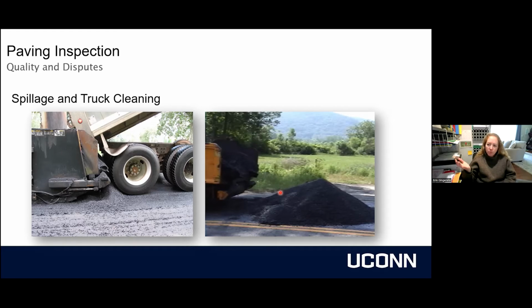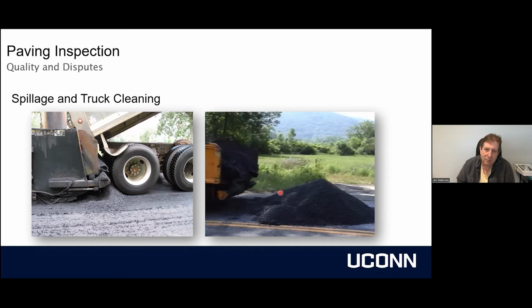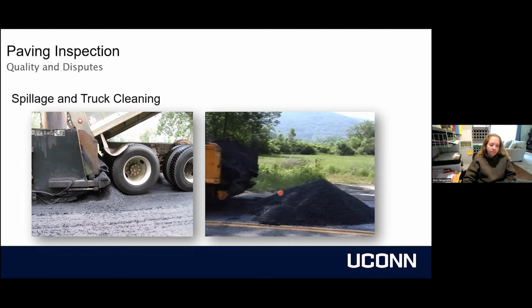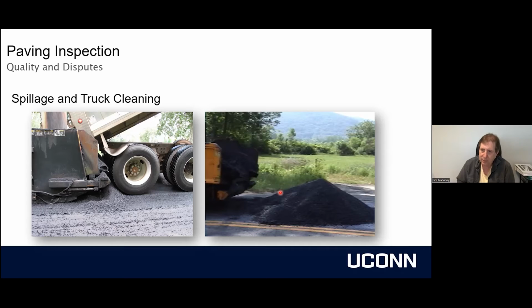Jim, is that pile garbage, basically? That pile can actually be loaded back into the paver hopper as long as it's warm enough. Okay. So you come in with a front end loader or something, you can actually pick it up and put it back into the paver. Sometimes though, it takes a long time to get the front end loader there and it cools off too much and then it does have to be thrown away.